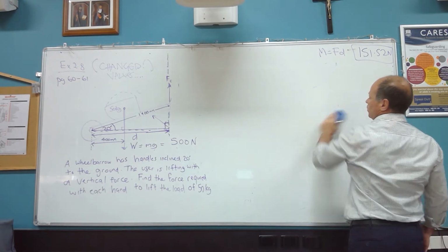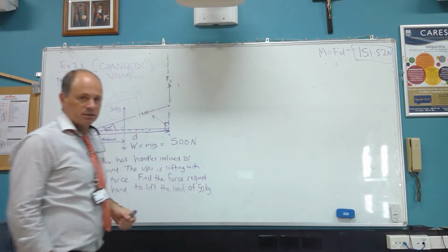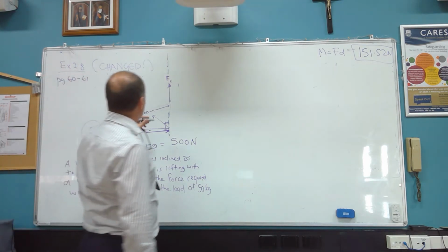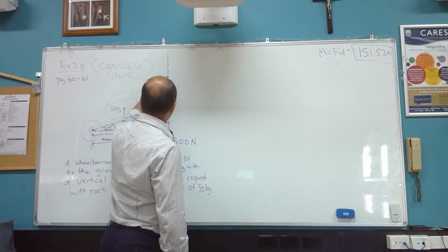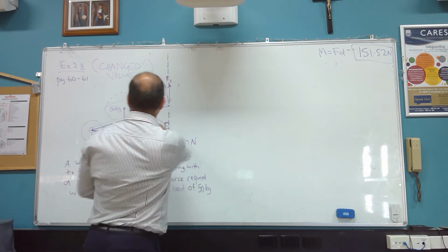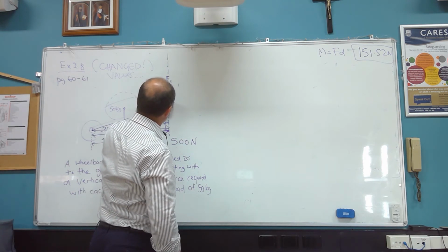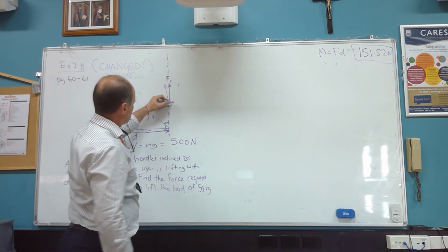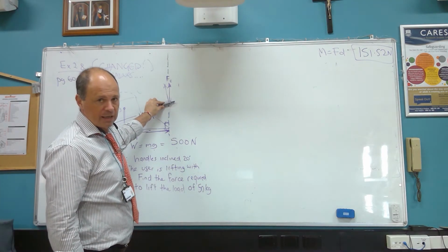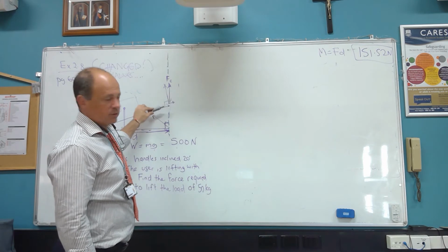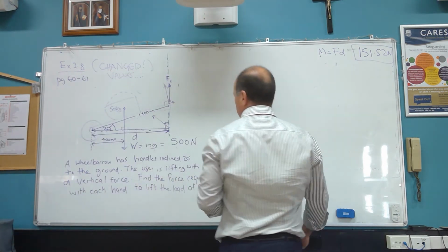Okay, so when we're given this problem here, we're going to use components of vectors this time. So we want to work out the component that is at 90 degrees to this arm, which is 1400, and that will then give us a component that's parallel with the arm, okay, 20 degrees, and one that's at 90 degrees to the arm. So we need to work out those components.